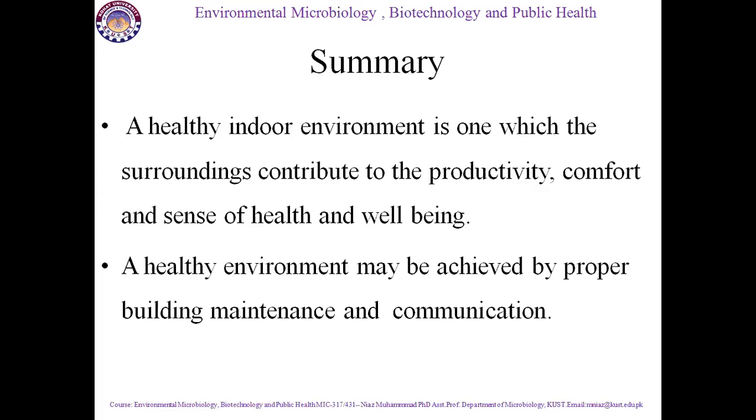If air flows inside the building, and minute contaminants are present inside the building, they will be diluted in the outdoor air concentration, and automatically they will reduce the concentration of the pollutant inside the building. The toxic or hazardous level inside the building will be at a mid level, and that will not affect the health of the individuals who are living there.